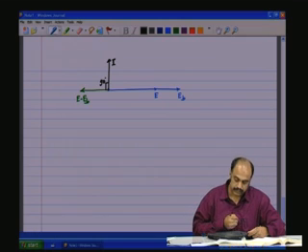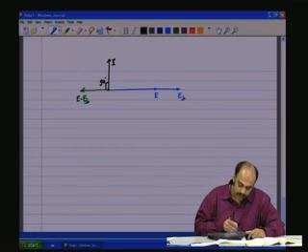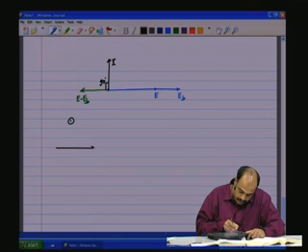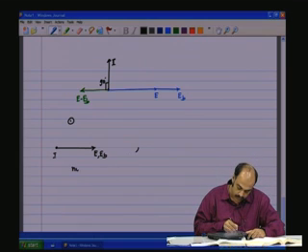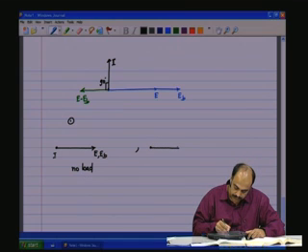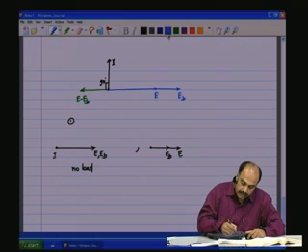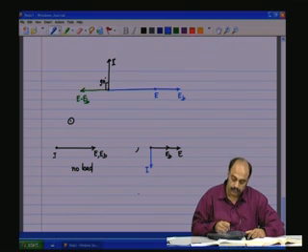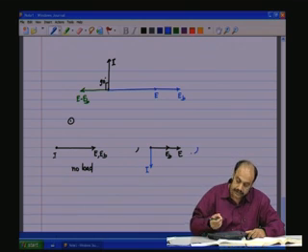This is 90 degrees. So we have now three nice situations. First situation, we have E and EB, current is 0. This is no load. Second situation, we have E and EB is lesser, and what is happening to the current? Current is lagging by 90 degrees.